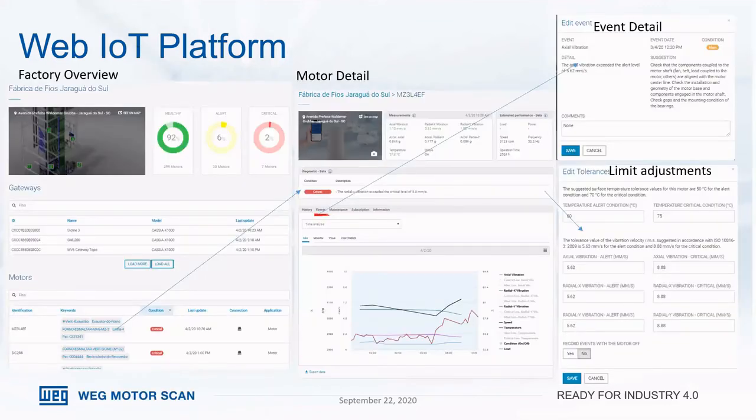And here's just some screens that'll show you some different features where we'll track the different vibrations, whether it's radial XY, or axial vibration. We'll estimate speed, temperature, and there's even some ways to insert how loaded the motor is, which are some calculations.